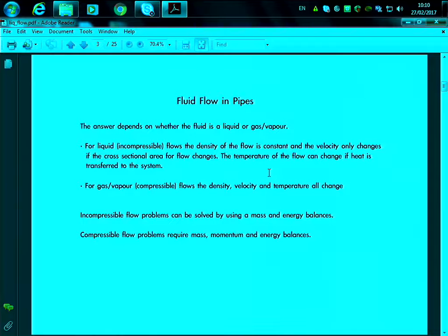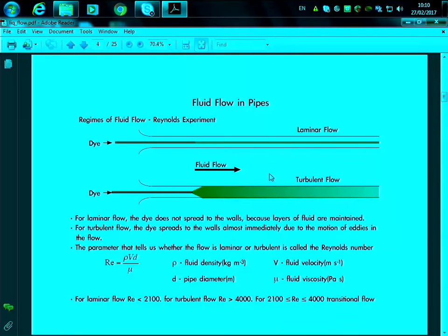So if we were having a pipeline, a horizontal pipeline, and then we had a laminar flow, and we suddenly inject a dye, then we will look at very small dispersion of that dye through the y-axis. Okay, so normally the dye will conserve its, let's say, direction, and it won't disperse. And that's because the movement of the liquid is basically as if we were having sheets of liquid going through, and there's no mixture really on the y-axis.